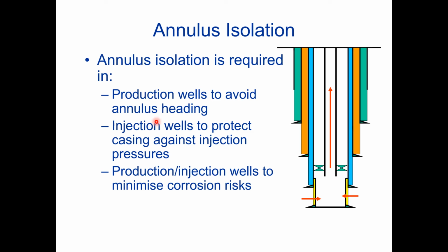For pressure maintenance or EOR or whatever, we need injection wells to inject oil or gas or water for secondary recovery. The other one is disposal. Sometimes some produced water or cuttings during drilling are injected in a disposal well.